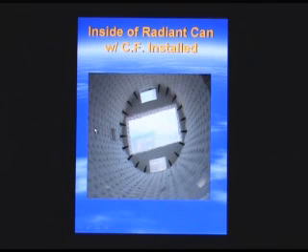But behind this, which is not shown, is the carbon steel material with an asphalt water resistant or non-permeable coating to keep the flue gas from condensing, because it will condense on there. That's another reason why the bottom of the heater has the castable refractory, so that there's enough heat on there that the base floor will run at a high enough temperature to vaporize any condensate.